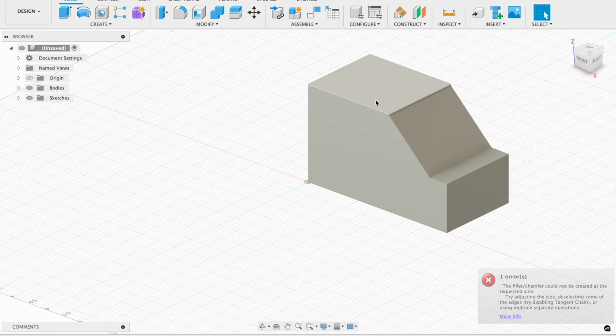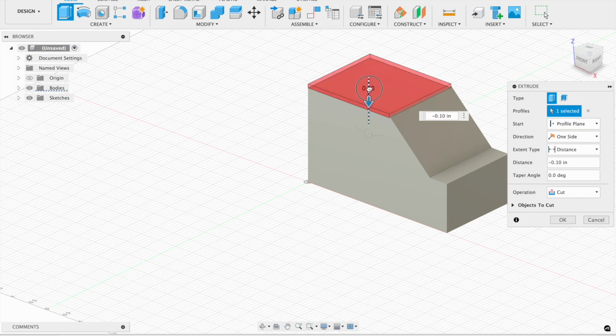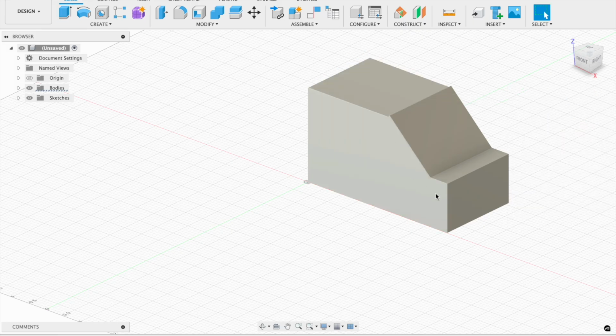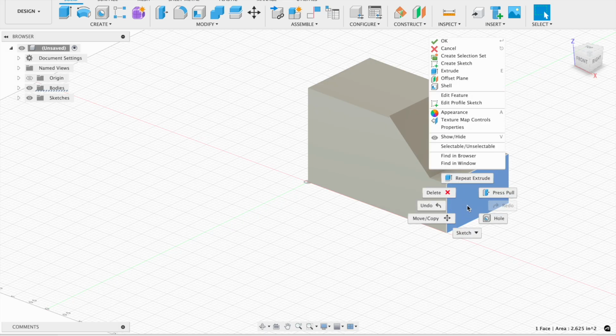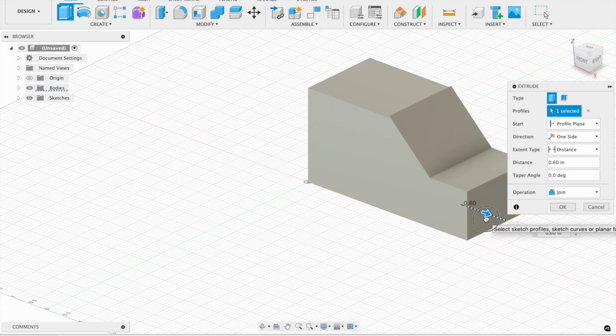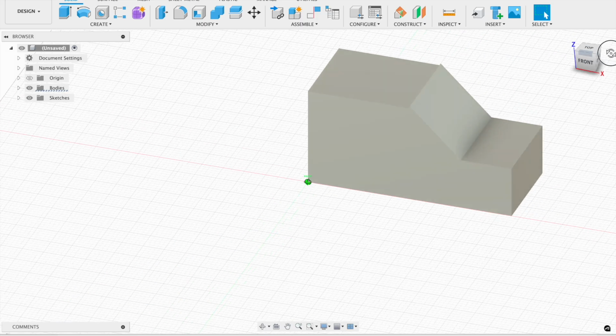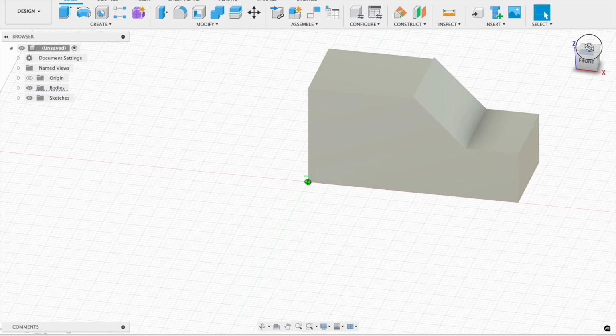So I'm going to emphasize the difference between the press pull tool and the extrude tool. The extrude tool will extend or cut into anything from a closed geometry. The press pull tool does something very similar, except it won't do all shapes. If it's a new shape added onto a solid, like a circle you added at the top of that food truck, the press pull tool won't extend that.